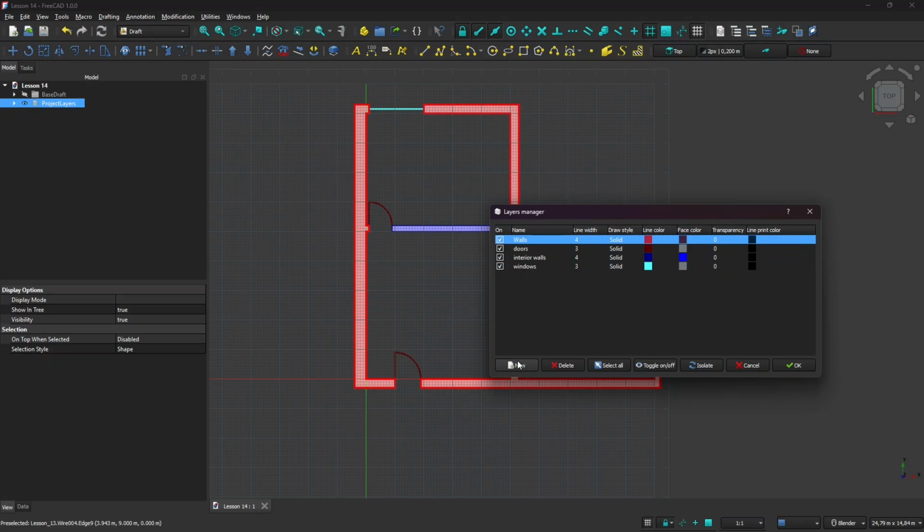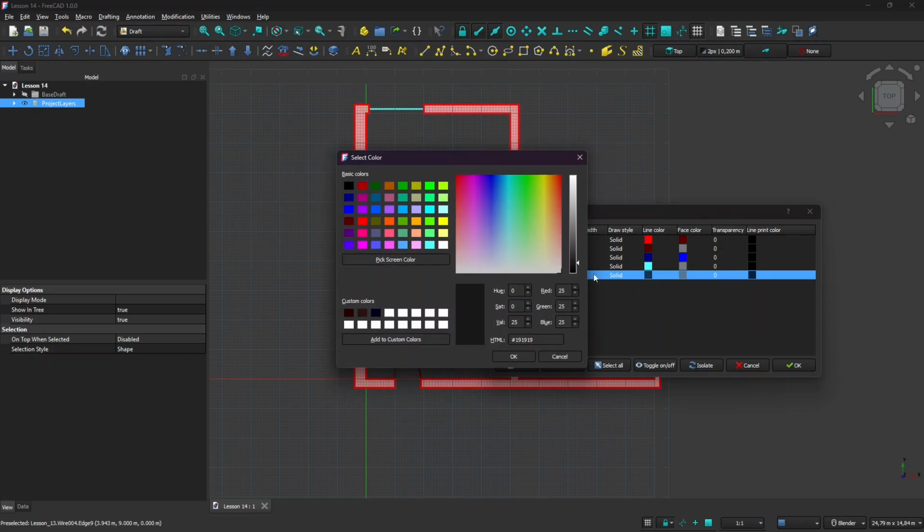So for example, the things that are on the pavement or furnishing, things like that, are going to be less thick than this. So let's create a new layer. Let's assume I need to do something that is on the ground. I can call this "on the ground" or "non-section" or "not section", something like this. You can call this however you want. This is going to be really thin, so let's put this at 1. Also visually, you can use a color that is not as strong as the others. So this one here could be fine. Let me just double click here and choose another color. You can use the picker here. You can also pick a color on the screen.